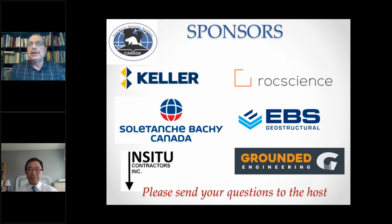The temperature is very important. If you have huge amounts of concrete poured in the same day into one hole, especially the piles for the huge towers that are of large diameters, like 1.2 to 1.5 and sometimes 1.8 meters diameter piles with 50 or 40 meters length, you're pouring this concrete in one shot, in one day, in a continuous process. You will have thermal effects on the concrete very clearly. So you need to have your temperatures controlled while you are bringing the concrete into the site.